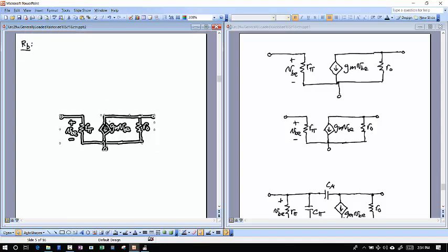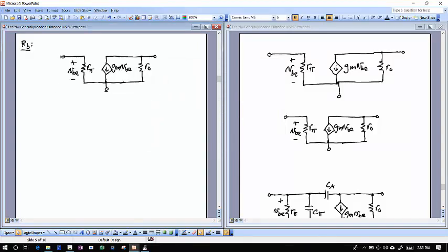All right, so I want this little RB, which means I have to do a small signal analysis, and I'm going to do that, at least at first, by using my hybrid pi model. And so anytime you encounter something you don't recognize, plug in the hybrid pi model. Don't be afraid to do it, because you might need to do it. And I will tell you later on what you can recognize and what you can't recognize. But when I use the word recognize, it's a very important word, because that's what circuit analysis is. It's all about recognition. If you can recognize things that you've seen before, that's how you can dissect an enormous circuit into something much easier to deal with. Okay? All right, so here's that hybrid pi model.